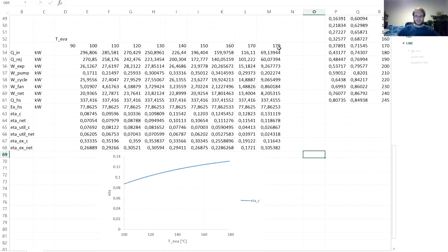That's because it's just the thermodynamic cycle, and of course it's based on the second law of thermodynamics. A higher temperature difference in the cycle, a higher mean temperature difference of the heat addition and heat rejection, results in higher efficiency. So by this you could say that increasing the temperature of the evaporation would be a good thing.